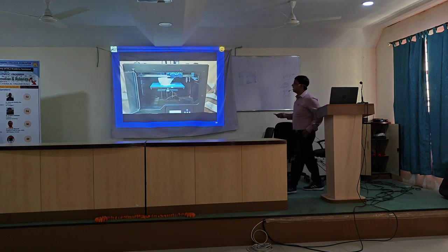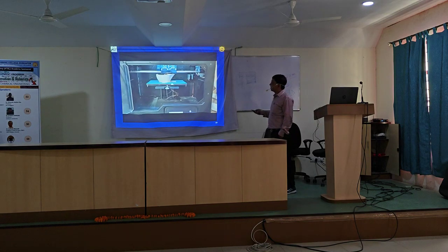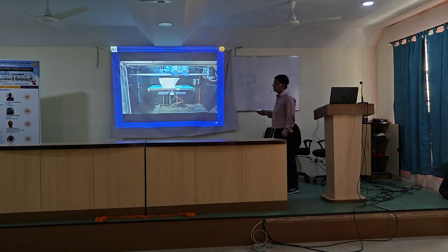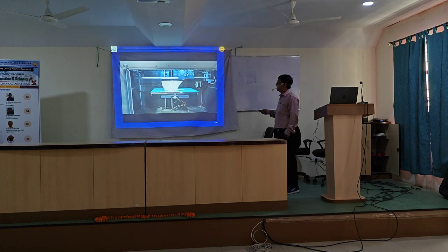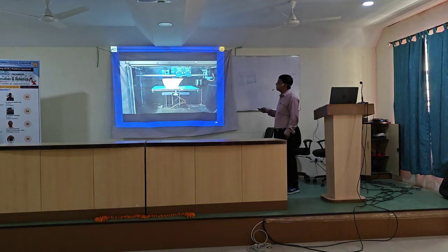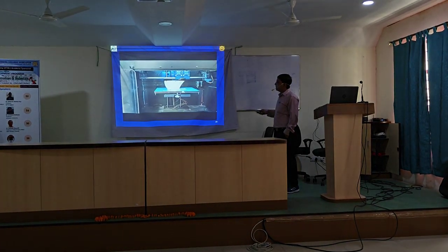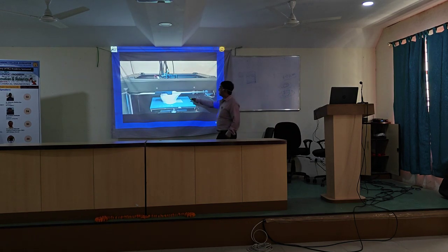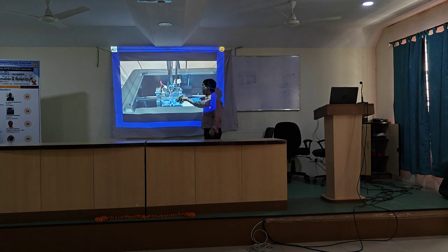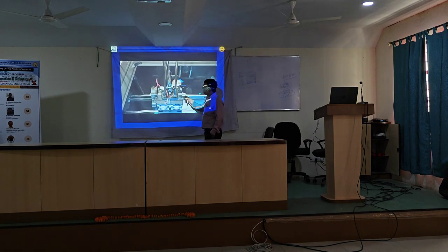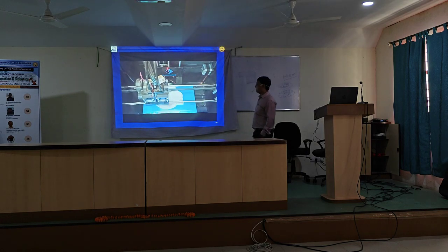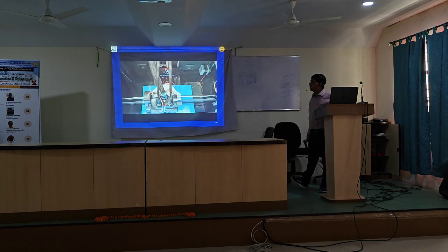During COVID, we developed our 3D printed mask with our tabletop machine. Here you see XY movement is provided to the head, and intermittent jet motion is provided to the platform. The mechanism for the platform is a screw-nut mechanism. For XY movement, the mechanism is a timing belt pulley mechanism with linear guides.